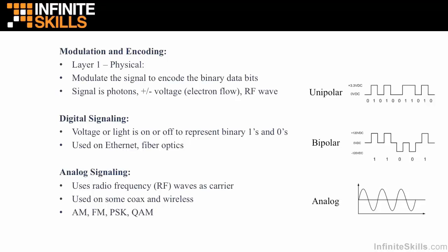And the good thing about this is, if you notice, in between each binary bit, there is a return to 0 state. In other words, two 1s in a row are clearly delineated because I send you out a binary 1 at 120 volts, but then I return to 0 volts for a period of time. And my second one is coming, okay, here it comes, there's the next 120 volts to convey my second binary 1.